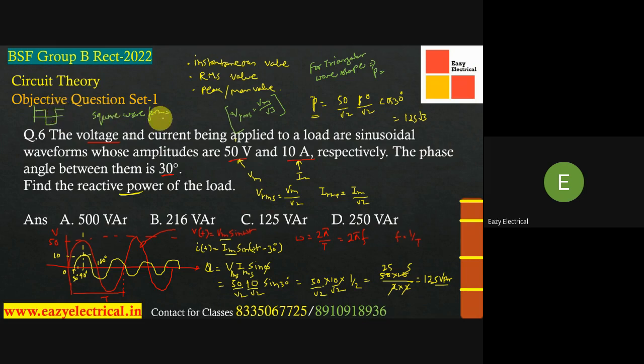The maximum value, the average value and the RMS value become equal. The RMS, average or maximum values are all the same. They do not have different values. So whatever is Vdc or Vaverage, that becomes equal to Vrms, and that is also equal to Vmaximum. How? If you see here, the maximum value is this one, and this one is also your RMS value, and this one is also your average value as well. So for the square waveform, this will happen.